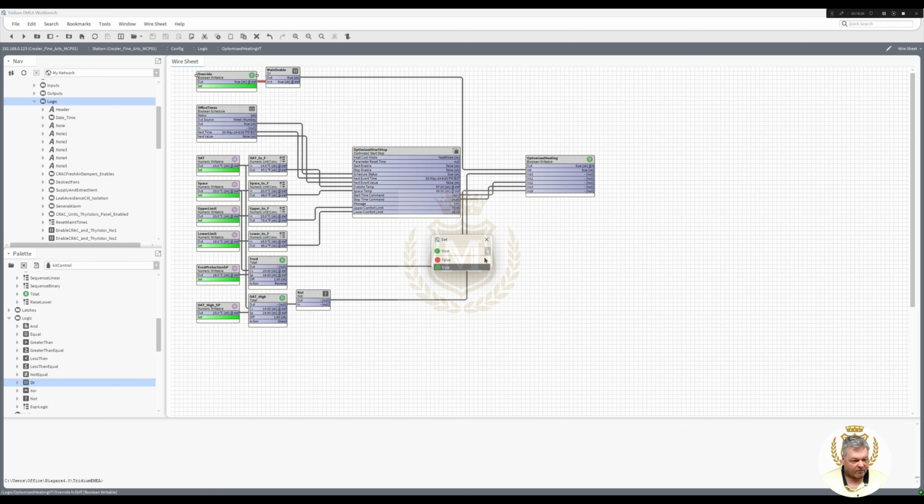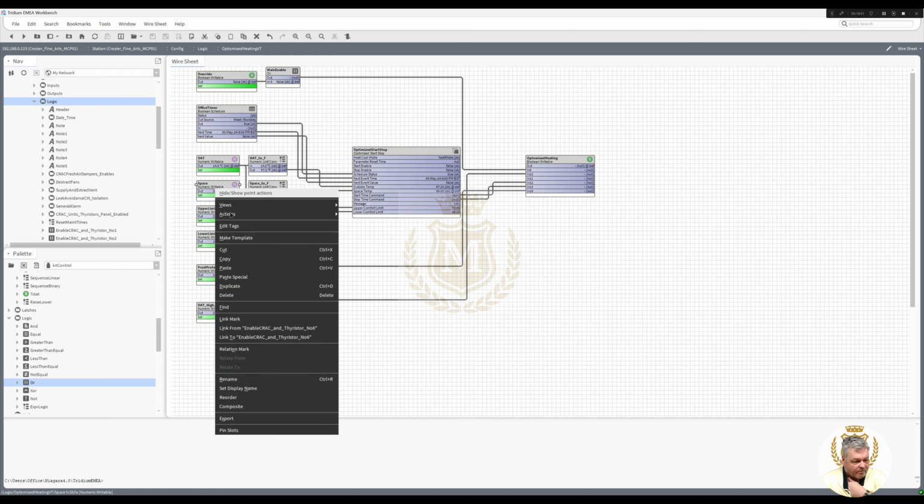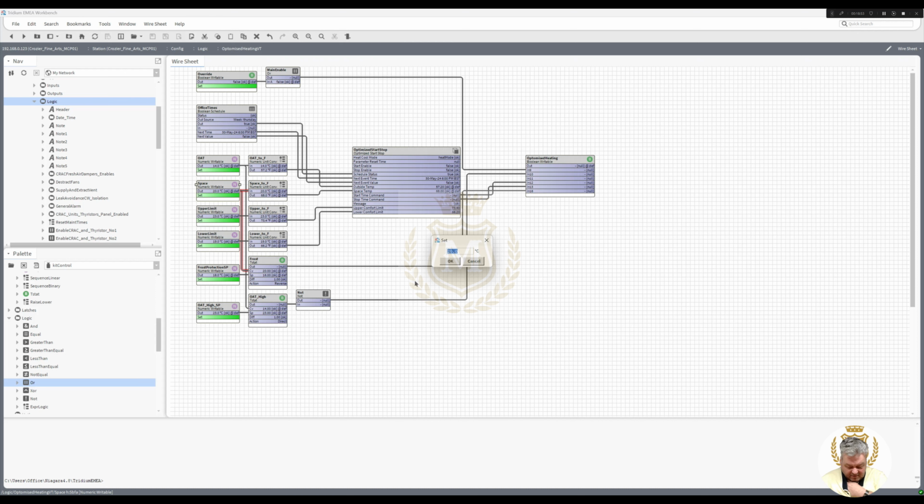Set that back to false. And now it's going to be using the start time and the stop time in here. But if we get a frost scenario, so space temperature, set that to 14 degrees so it's really cold in there. I think that's outside there, 14 space 14. So that's our true there and a true there. We're putting our output on for heating.